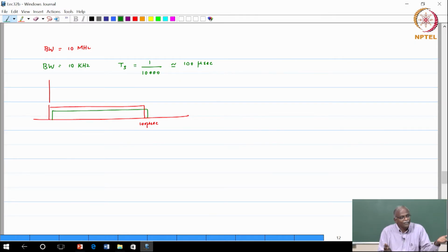So how much inter-symbol interference will you get? The previous symbol, let us say was transmitted as purple, you will get some combination from it, that is your inter-symbol interference, very small. So this is a case where ISI can more or less be ignored; you can treat it like noise, some small impairment.